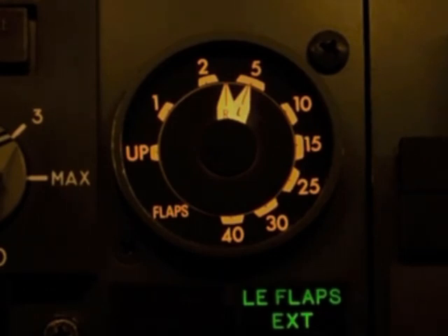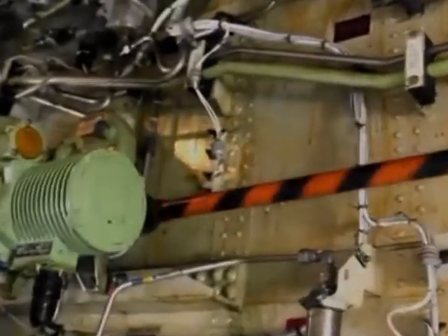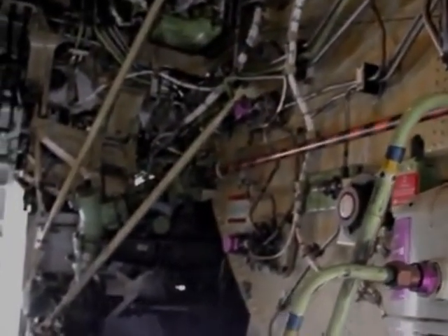In order to prevent asymmetry of the aircraft, and to prevent damage to the trailing edge flap drive mechanism, we have a bypass valve. When the bypass valve senses that there is an asymmetric extension or asymmetric retraction of the flaps, the drive valve will move to the bypass position and bypass the hydraulic pressure from the flaps, and the flaps will be stuck there.